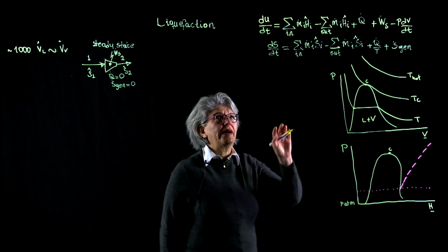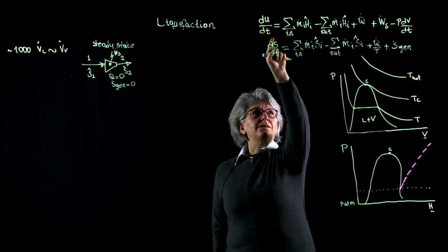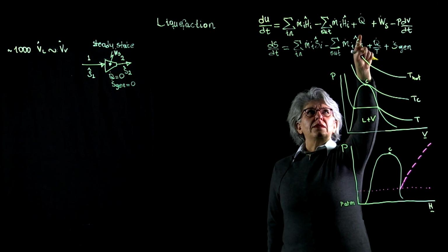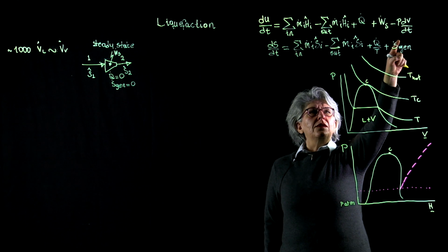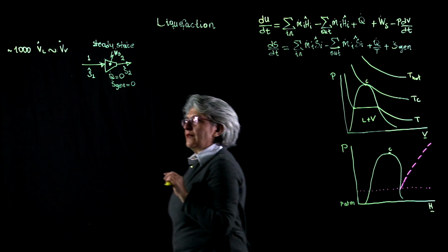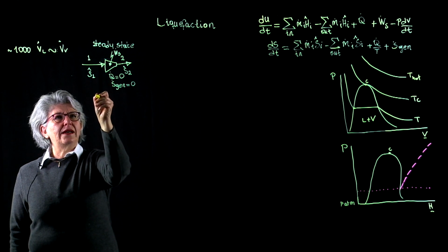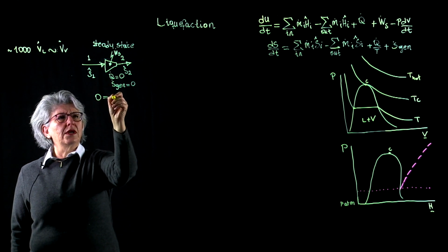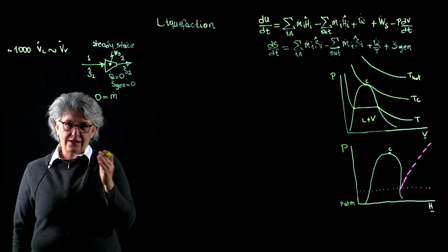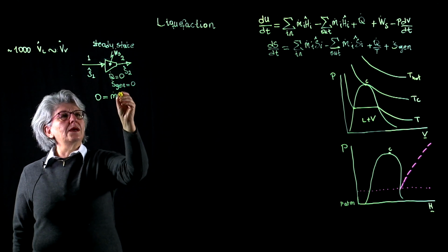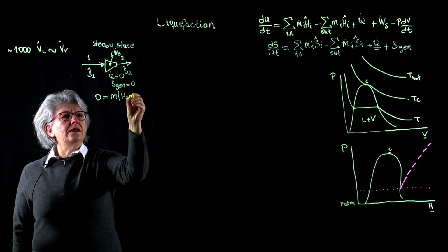When I do the energy balance, this is 0 because the process is at steady state. The process is adiabatic. The compressor is rigid. And around my compressor, I have my energy balance as 0 equals m dot, and of course, the steady state condition also tells me that the flow rate is constant in this process, H1 minus H2, plus shaft work.